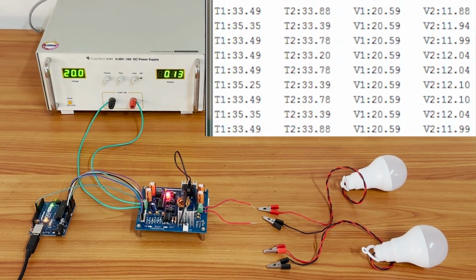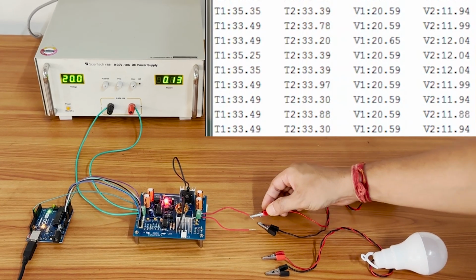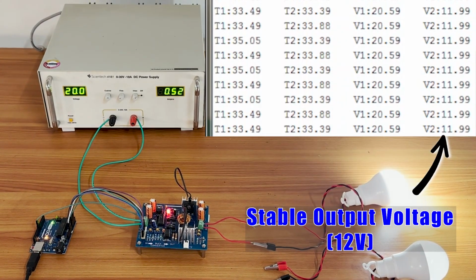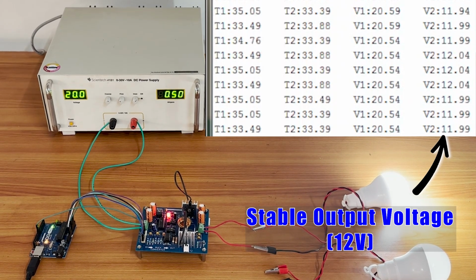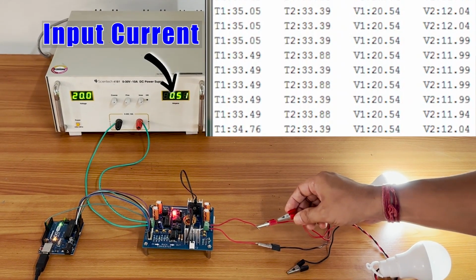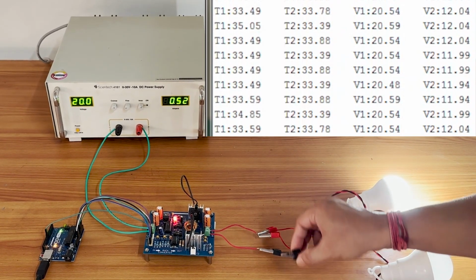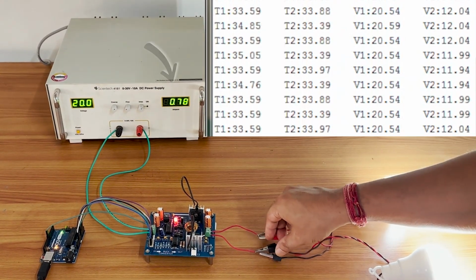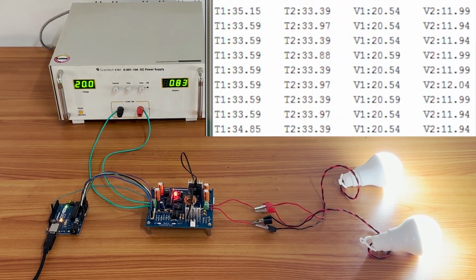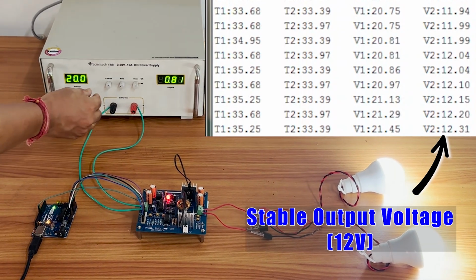We firstly start by connecting one of the LED lamps to the output terminal. You can observe that the output voltage is stable and constant at 12 volts. However, the input current has increased to 0.5 amperes. We again increase the load by adding another LED lamp at the output terminal. Input current has now increased to 0.8 amperes. But the output voltage is perfectly stable at 12 volts.